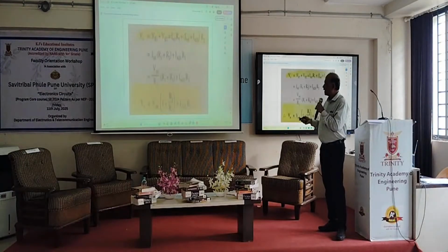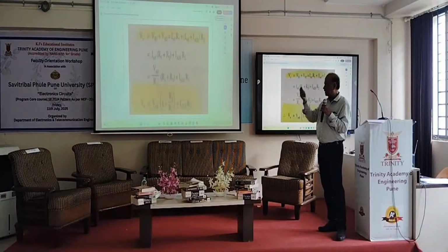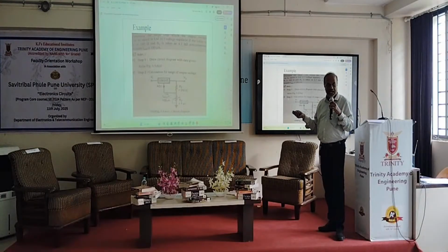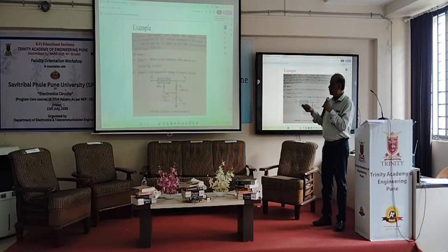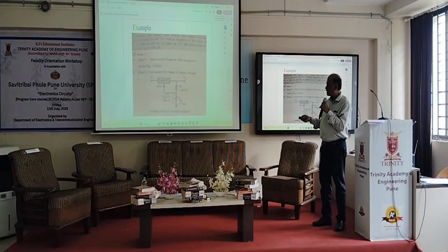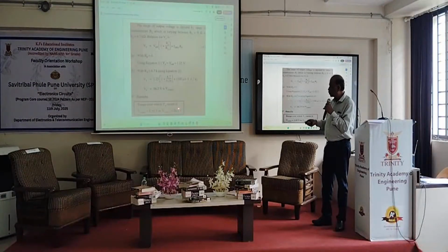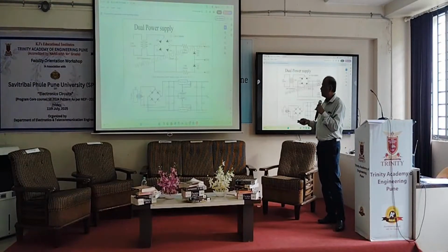This is variable IC regulator. This is some particular derivation which might have been done long back. This is the example which can be solved and which can be asked in the exams also, that what is the output voltage for different values of resistance given over here. And here you can see that output voltage is from 1.25 volts to 26.2 volts. So this is the formula and the substitution of all the values over here.